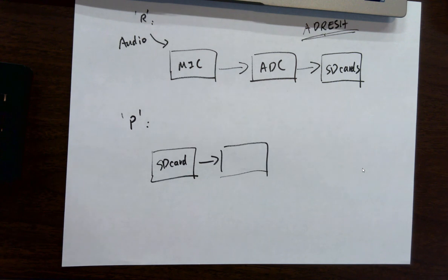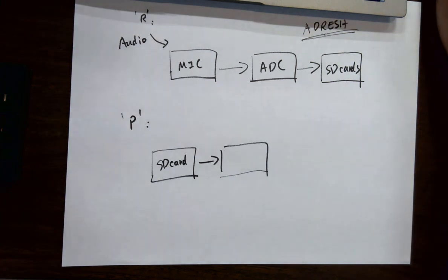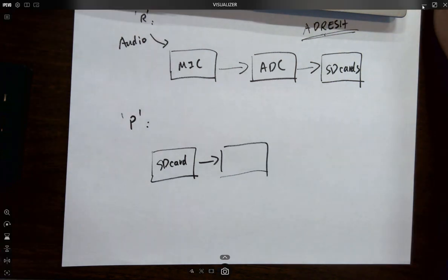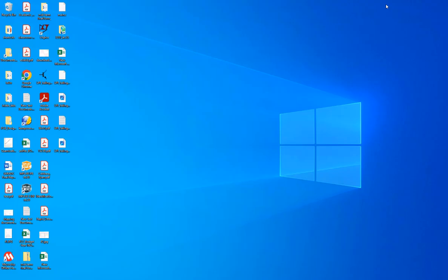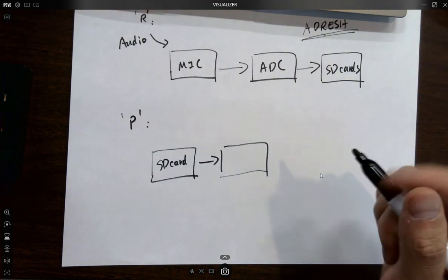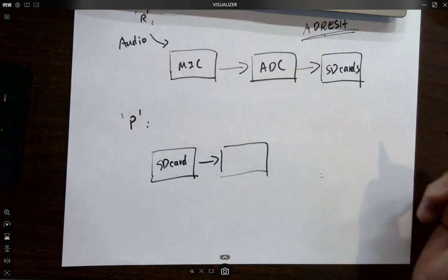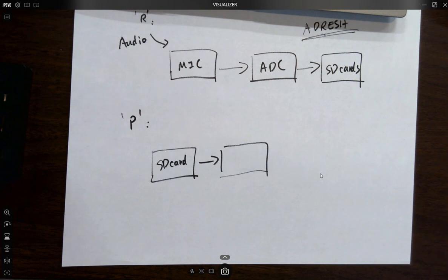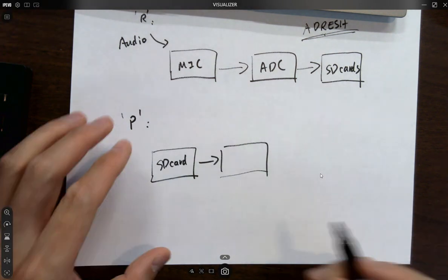That's why we learned this DDS on Monday, right? So how does that work, remember? How do we use direct digital synthesis to convert a digital signal in 8 bits to an analog signal? How does that work? What's that? Low pass filter, yes, that's right. And PWM, so combined, right?